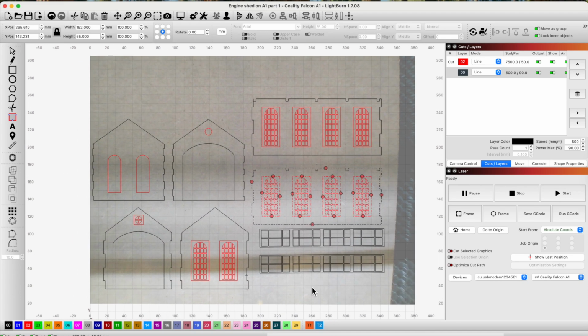All right, so I've looked at the camera, and it is showing everything on the piece of wood that I want to burn. Now what I was saying about this is, generally if you put this first and this second, then the interior cuts that I'm making, all of these cuts, will happen first. And if there's any movement from what you're doing, then it won't dislodge. If you cut these first and there's movement, then these will be offset, displaced, and not where they should be. So you always make your internal cuts first and your external cuts second.